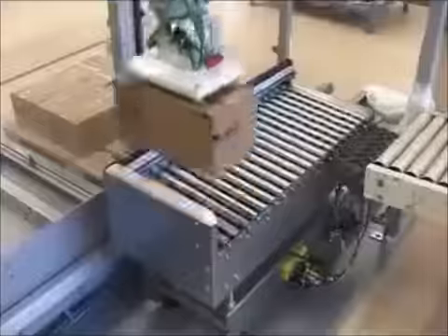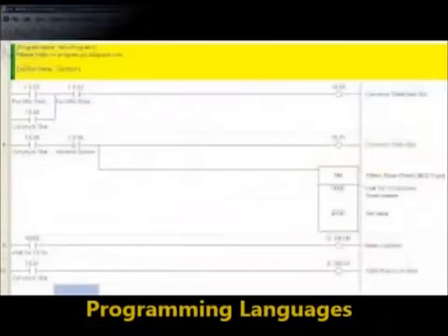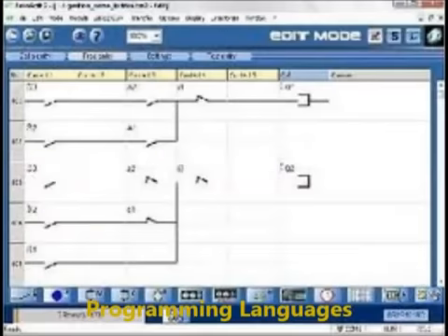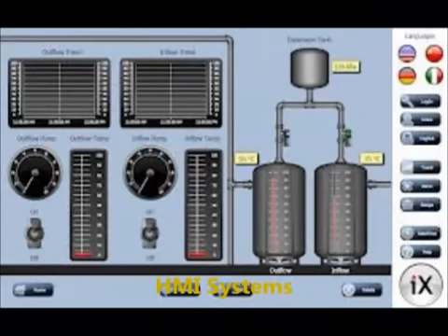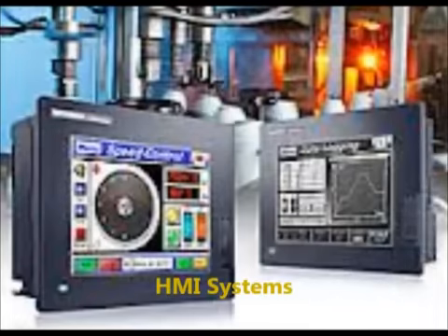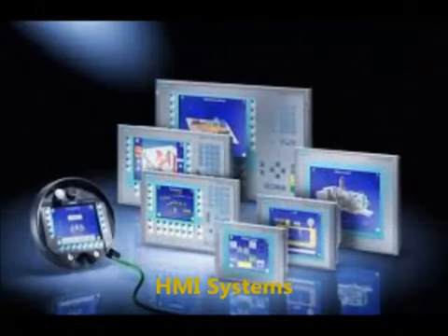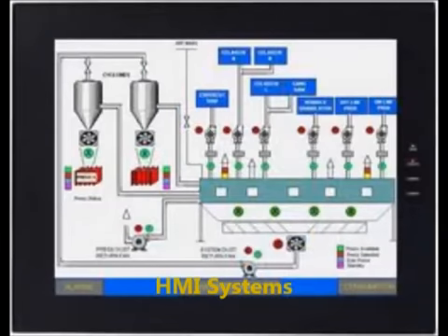There is a large amount of PLC manufacturers, each having a range of models with different functionalities. They all have in common the operating philosophy of a PLC, and standard languages to be programmed, like ladder diagram, sequential function charts, function block diagram and structured text. Normally for communication with the operator an HMI system is used, which has the mission to operate the electromechanical system, graphical animation and process data, alarming, data logging, trending, report generation and more.